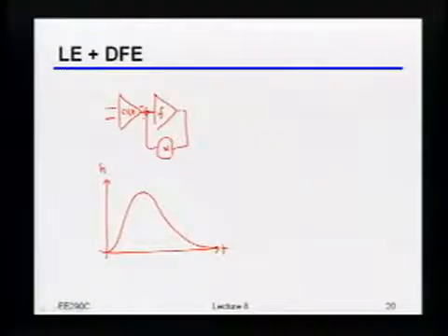Well, when I apply just the continuous time linear equalizer, keeping in mind that when you apply linear equalization, that generally means that you have to throw away DC gain, what would the, and let me maybe draw where the sample points are here. Let's say the sample points are something like this, okay? Roughly speaking, if I just did everything with a linear equalizer, what would that new response look like? Or what would you want it to look like? And okay, maybe there's even a precursor here, but what should that new response look like, just qualitatively?